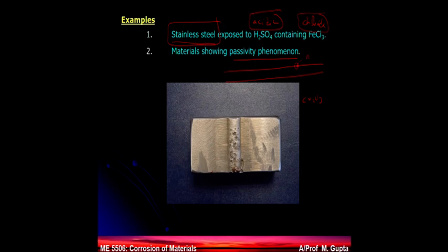This is anode because the protection is gone. And you have miles and kilometers long cathode here. So no matter how fast the anode or that pit dissolves, it is always supported by the cathodic reaction because the cathodic area is so big. So immediately the pit will cross through the thickness of the wall and the system will fail.